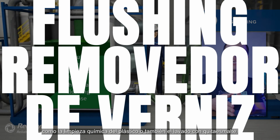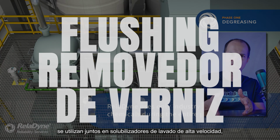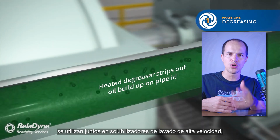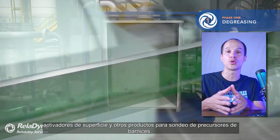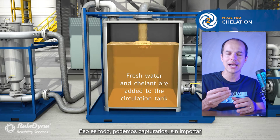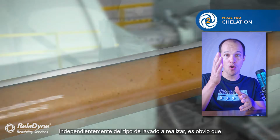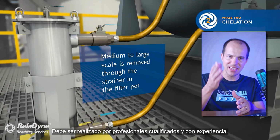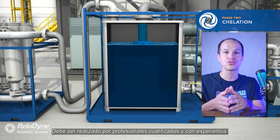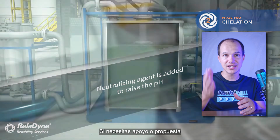Finally, to conclude the main topic of today's video, it is also worth highlighting another type of flushing with cleaning additives, better known as chemical cleaning or flushing varnish remover. In that case, solubilizers, surface activators and other products for removing varnish precursors are used together with high-speed flushing. That way, we can capture them. Whatever type of flushing is to be performed, it must always be carried out by qualified and experienced professionals. The standard itself says so.